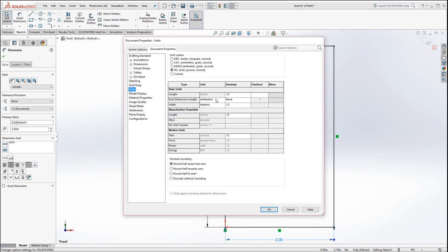It automatically transforms it to the proper dimensions. It's not like older systems where you'd have to rescale it to whatever. You just kind of change it and it's done. So over here you'll see the length and we see decimals. This is actually the decimal places that we want to see. So if you click over here you could change it to 3 decimal places, so 0.123.